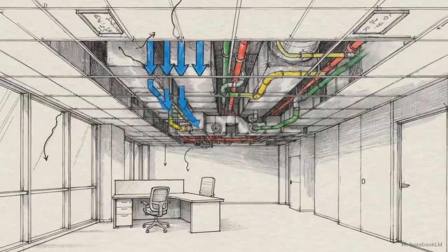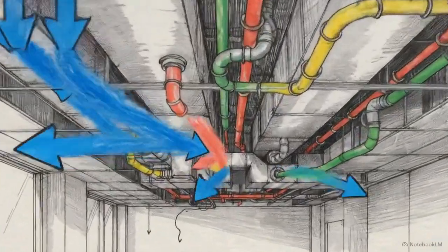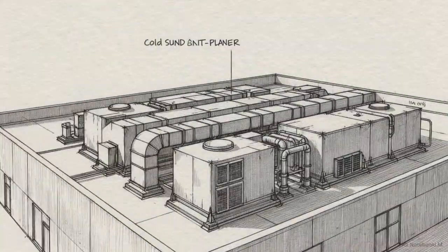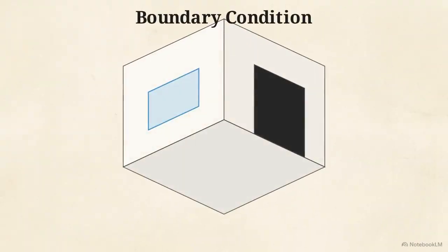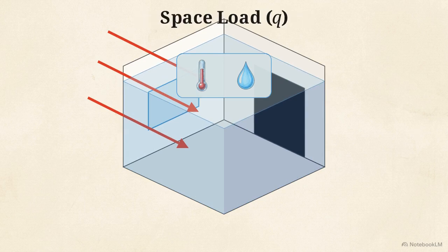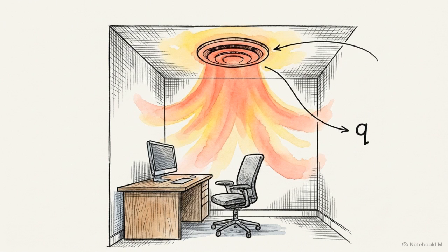The primary objective of modern HVAC design is determining the exact thermal capacity required to heat and cool a building. We start by calculating the heat gained and lost through the boundaries of a specific room. This gives us the necessary volume of air to maintain comfort in that physical space, a value defined as the space load. In standard engineering nomenclature, this localized space load is represented by the lowercase variable q.